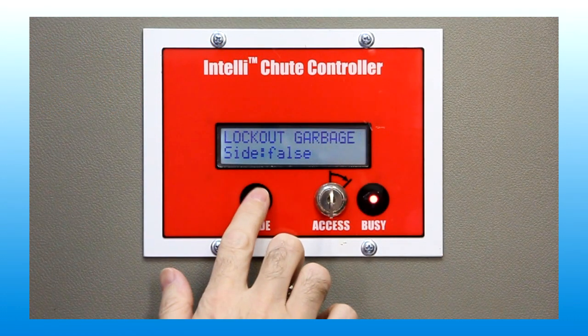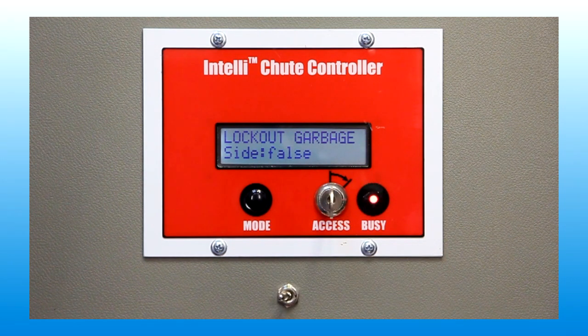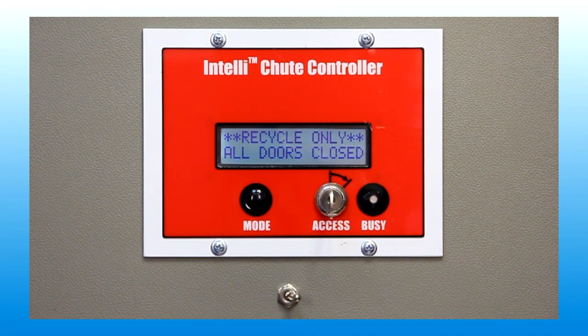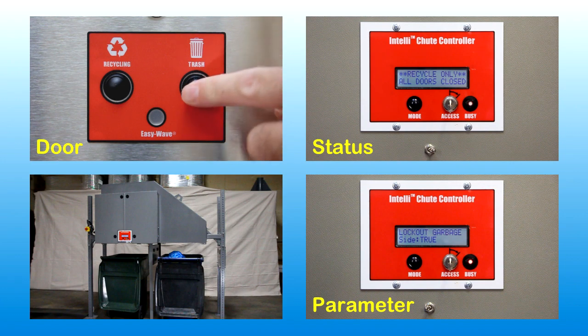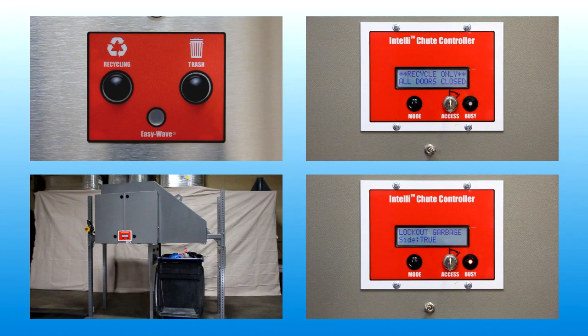The Lockout Garbage Side parameter can be enabled or disabled. Select true or false. By default, it is disabled, and the BiSorter operates normally. To enable, select True, set the toggle switch back to the enable position, and now all garbage side cart signals are ignored. The first time any intake door selection switch is pressed, the BiSorter moves to the recycle position and will not return to the garbage side again. Both intake door selection switches will continue to operate, but all waste, including garbage, will be sent to the recycle side containers. In this mode, the BiSorter operates as if the garbage side does not exist.